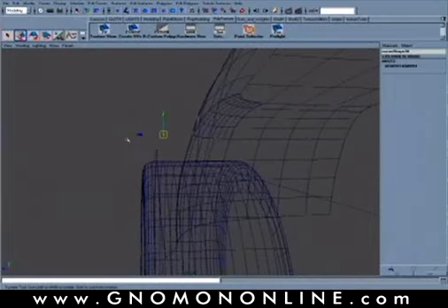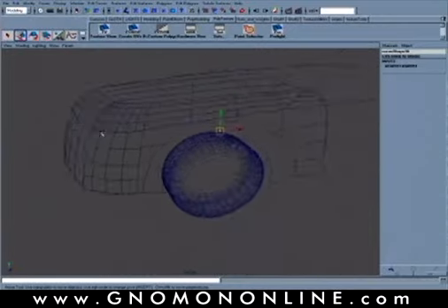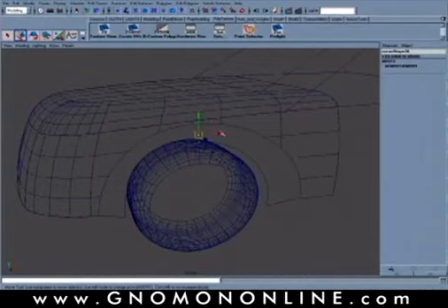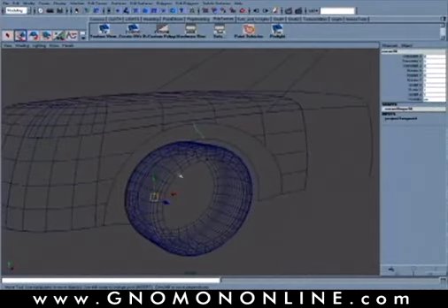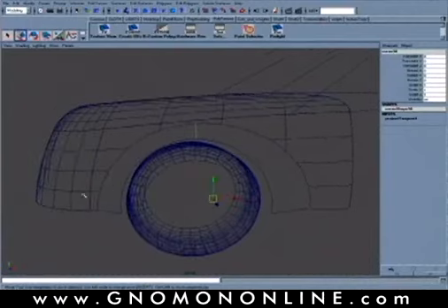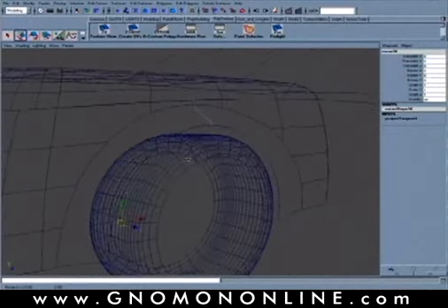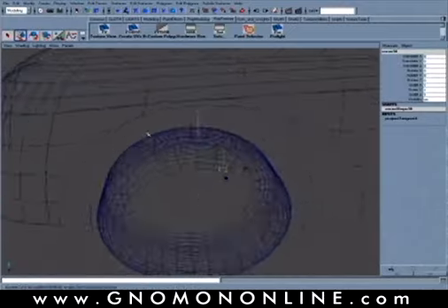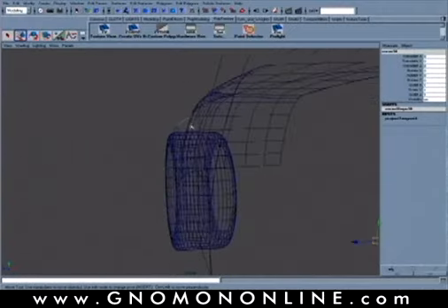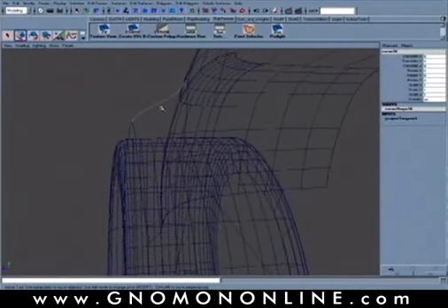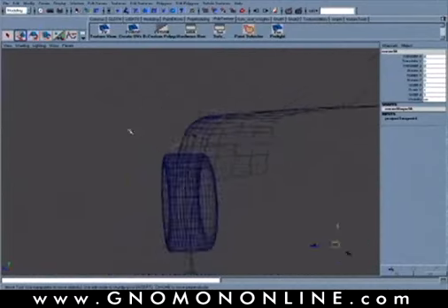Okay. And this we're really just looking at a single wheel opening. You could break this up into several sections and do separate squares. This one's a little bit faster in that you're only dealing with really one sweeping surface that's going around here, meaning that we could extend another surface coming off there. Or you could even break this up into two separate curvatures, one for the negative curvature, one for the positive. So each one of these could actually be a break here too. Just gives you more control but more complexity.